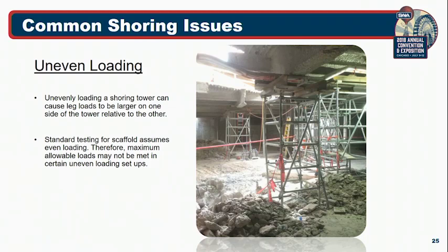However, as what occurred here in this picture, there was a pipe in the way up top, and so the contractor was forced to shift the top support beams over the front 2 legs. And so not only does this increase the load to the front 2 legs, notice that both of them buckled in the same direction without engaging the back 2 legs. And so the actual design load it buckled under was less than that the manufacturer had published.